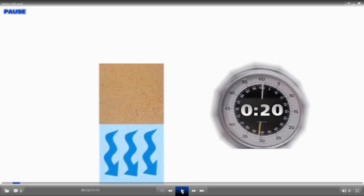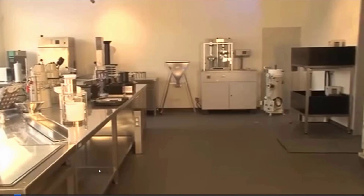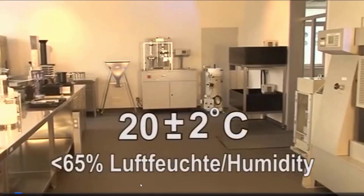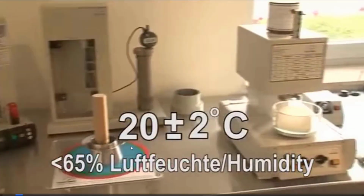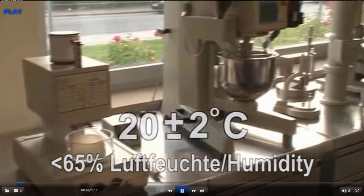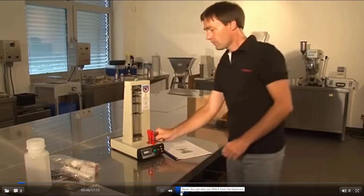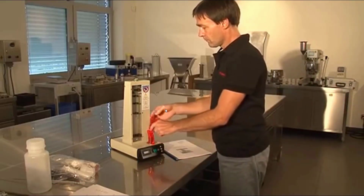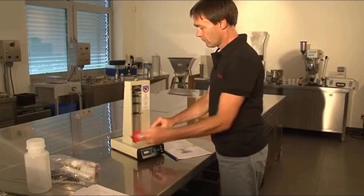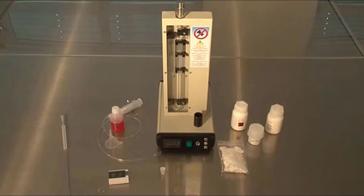That time is recorded as time t on your stopwatch. This test is conducted at 20 degrees Celsius, with relative humidity less than 65%. First, you insert the manometric liquid into the manometer by injecting it using a syringe.